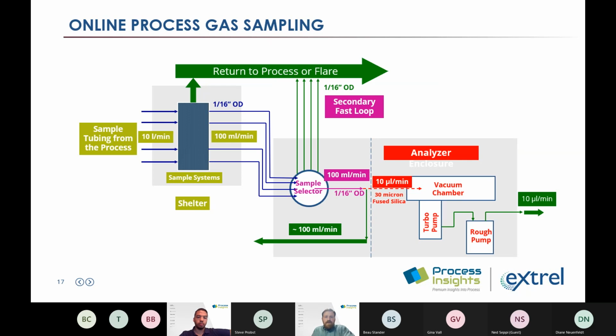Okay, a note on the sample system itself. A flare sample system is pretty standard. Generally, you've got that heated umbilical that we mentioned. Typically, there's a pump because the flare gas is usually maybe a little above ambient, maybe it's at ambient pressure. And that pump is going to be delivering it back to a cabinet that's filtering it. And again, it's going to be a heated cabinet to prevent condensation in the sample system. And that's really what we've got here.